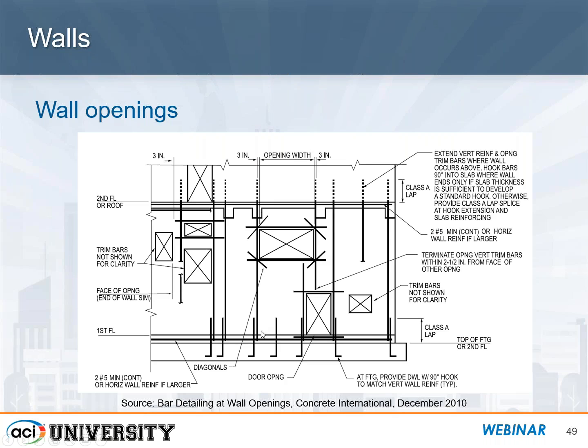Now that's not such a great detail to provide, and we'll talk about that on our next slide. If this were a large opening that went from the base up to the top of where it's shown here, then it makes sense to anchor that with a dowel bar into the foundation.